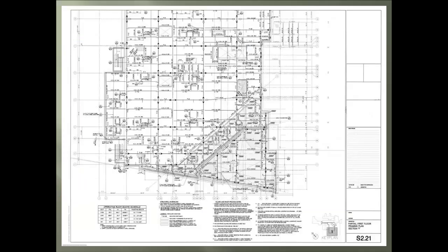These are some more important symbols. Number 9 is for drag cord connections. And number 10 is for headed stud count and location. Number 14 is for moment frame designations located on the plan view sheets. And lastly, this symbol represents the shop induced beam camber. And the last item is the location or segment of the project floor or level.